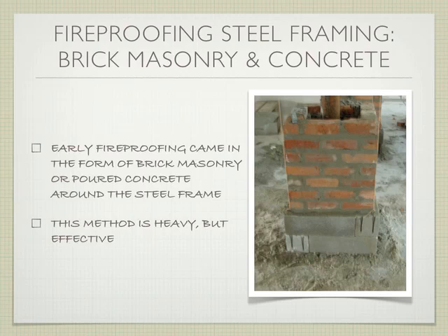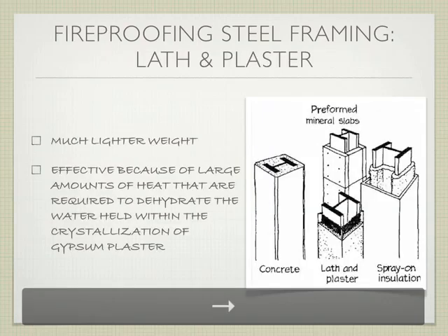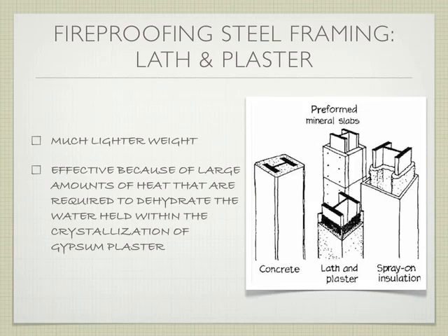The problem with this as a strategy, while it works and can look very decorative, is that it's really, really heavy. We're adding a lot of weight to the building without getting much for it. It's not providing structural value, just fireproofing value. So it's not the most economical way, because you have to increase the structure in the building to fireproof a particular piece. So we moved from covering it with brick or concrete to a much lighter weight solution,